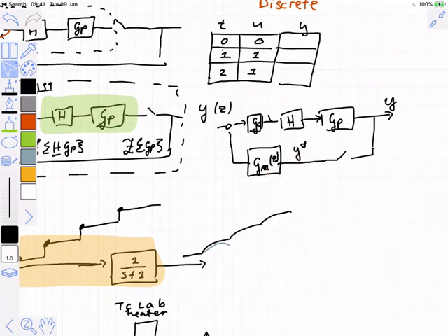It doesn't make much of a difference to the calculation, but it is very easy to overlook these things when you are just looking at the form of the equations, because it looks so much like the closed loop transfer function that you're used to doing by now just from memory, that you may forget that you're not allowed to take the Z transform of continuous systems in series.